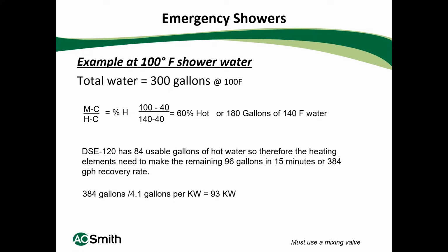Very well. Sure, a quick question came in regards to that 4.1 gallons per kilowatt. Can you talk about where that comes from? Yes. So it is on our spec sheet for our electric water heaters. It's below the chart, but 1 kilowatt will heat 4.1 gallons of water per hour at a 100-degree rise. That's a pretty standard rule of thumb in the industry.